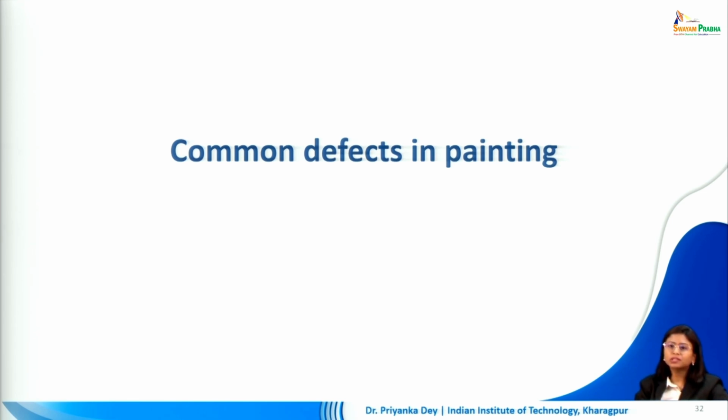So it's important for us to select materials which are suitable in different contexts. So let's say if we are dealing with a particular building which is exposed a lot to corrosive gases, we would want to select a paint material which is anti-corrosive. Otherwise, the durability of the painted surface will be significantly reduced. Which is exactly why all of these options that we studied will find application in some or the other location, weather conditions or building based on their usage.